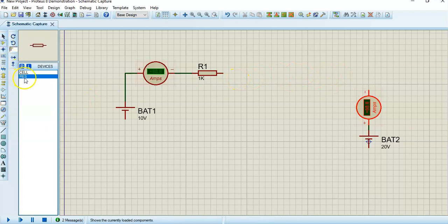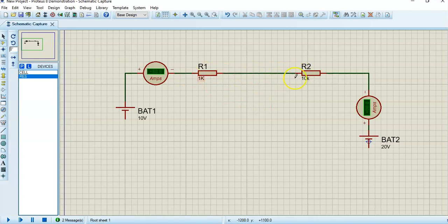and I need a resistor here. So go to the resistor, click. I'm going to connect this and here, and you need to connect these two as well, and you need 2 voltmeters across this. Because the current enters from here, this end of the resistance is the higher potential than this.